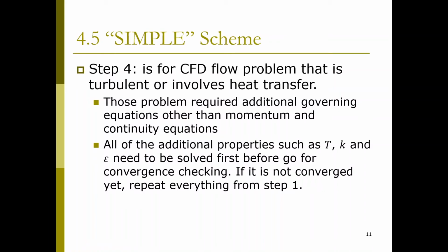Similarly, in the convergence checking, if the residual is very far away from zero, we will repeat everything from step 1, and it will keep improving until the value is very close to the correct value, and then it will be considered as converged and the process of the SIMPLE scheme will end.